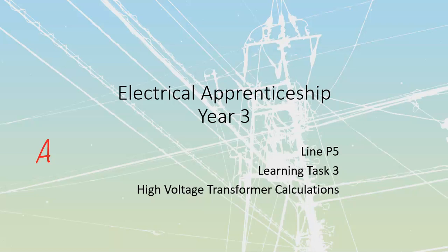We'll just draw through the first couple of steps. To neutral, we're going to go off at 30 degrees, and then to B, we're going to go off at 60 degrees, and then we start with the high side, and then we draw out all the rest of the low side, the C, and then we just match our transformer windings to form the secondary. All of that is going to be done the exact same, so we're not going to go through any of that inside here. We're just going to look at the transformer calculations that we're going to have when we are dealing with a high voltage transformer.